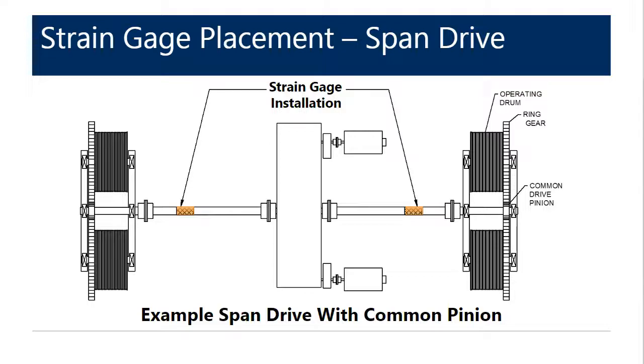With this machinery configuration, the total opening and closing force for a given side can be established, but not a corner total. The end totals must be assumed to be split equally on a given side of the span, as there is no other way to distribute the load between the pair of operating rope drums.